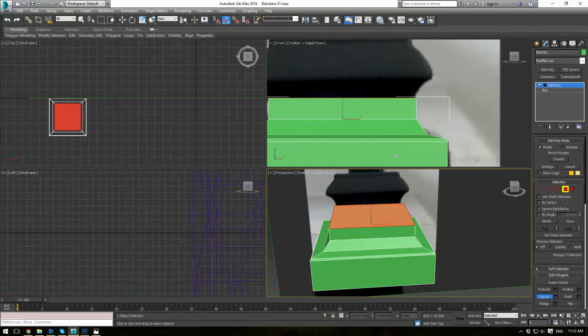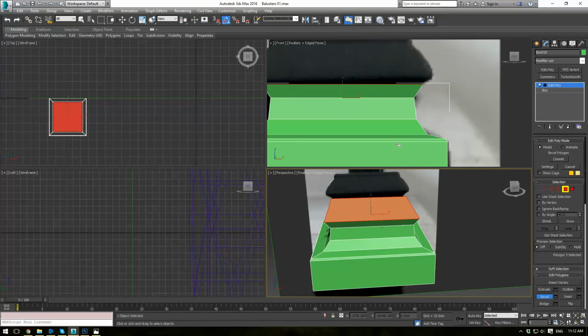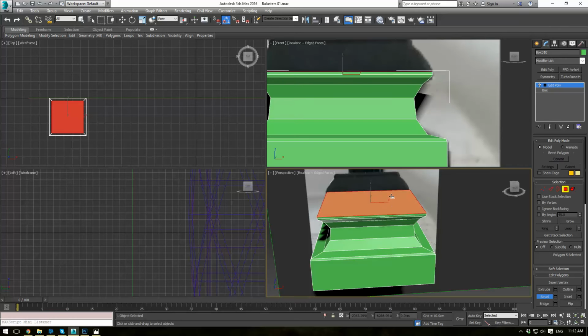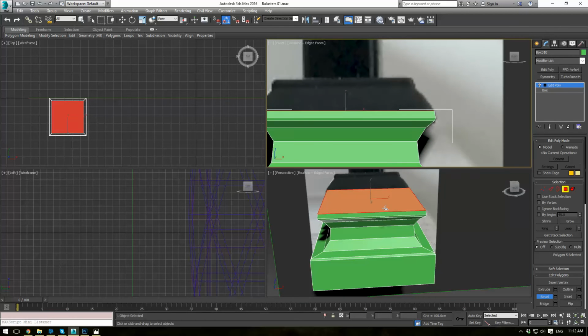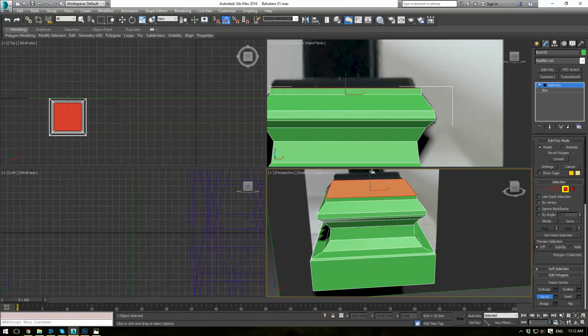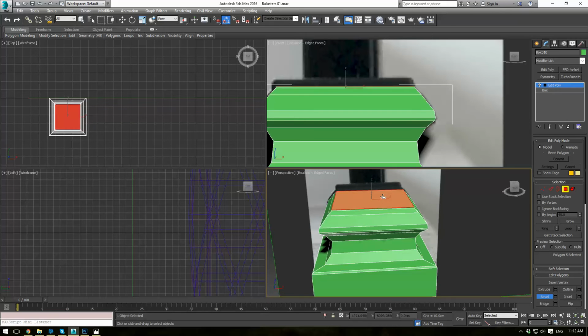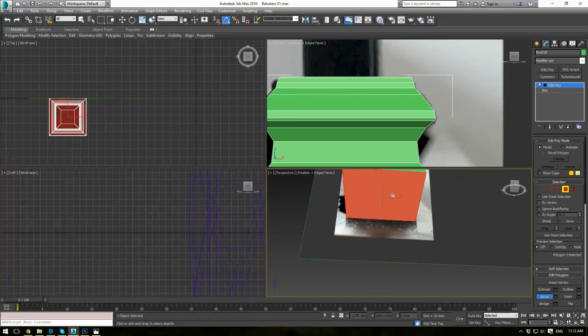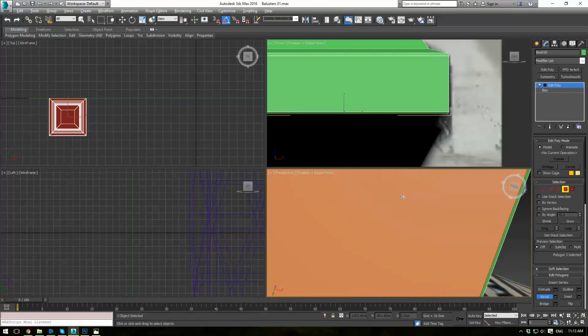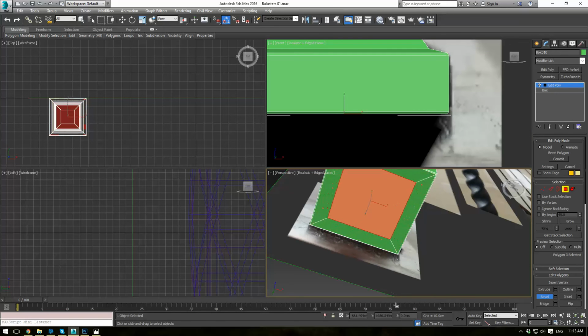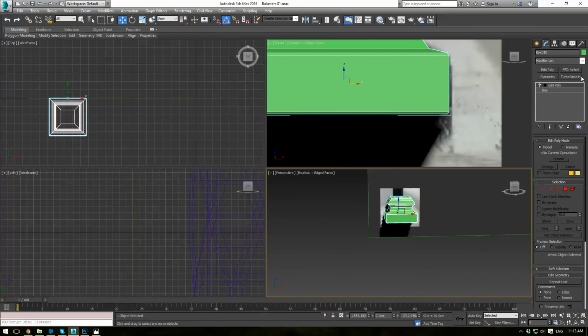And you can do this with a lathe modifier or something. There's a lot of ways you can get the same desired effect, but this just happens to be my favorite. Kind of lets me do a little bit of free-form modeling, if you will. Alright, looks good. And we're just going to do one on the bottom there. Alright, and just a basic inset. There we go.